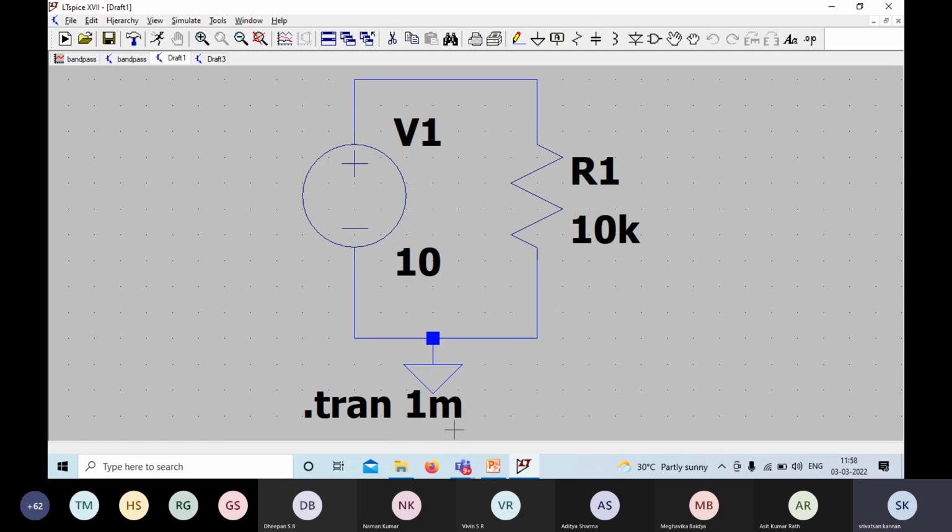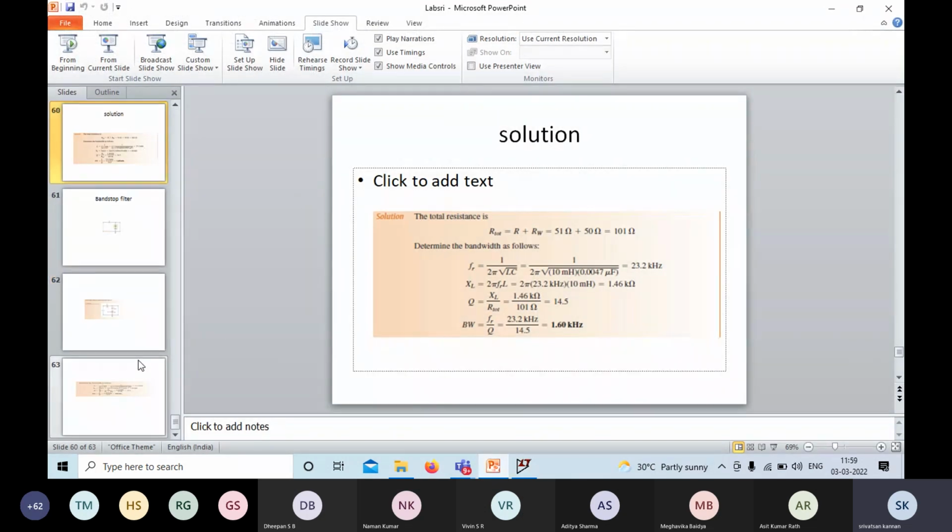What is the depletion region? Sir, it's the middle point of the PN junction where the charges meet. Yes, charges at room temperature. Some of the electrons in the N region cross the junction and combine with the holes, and similarly the holes near the junction combine with the electrons in the P region. This process will continue until a barrier potential is formed. The barrier potential for a diode made of silicon is 0.7, and for a diode made of germanium it is 0.3. And I'll show you the VI characteristics of the diode.